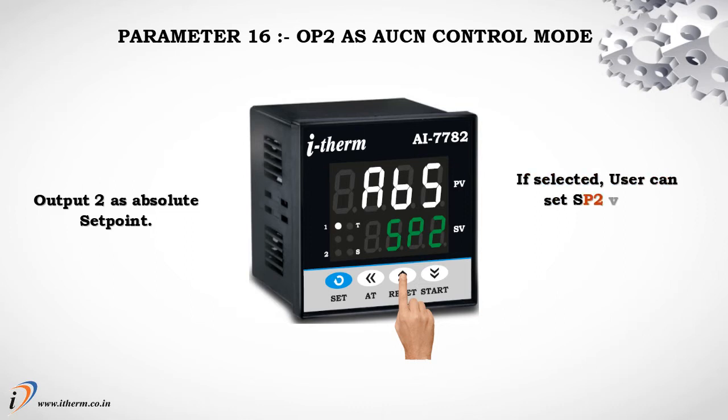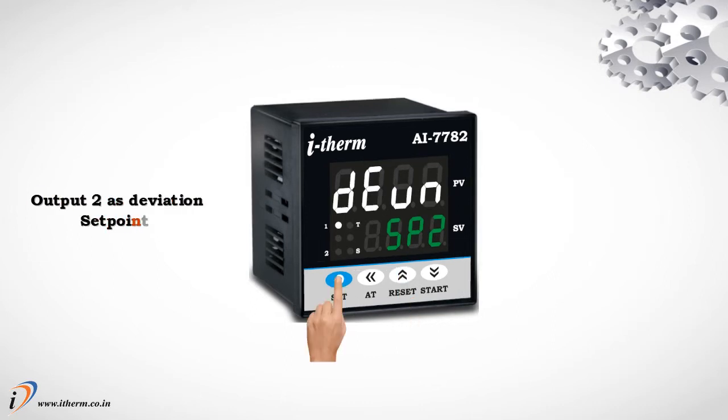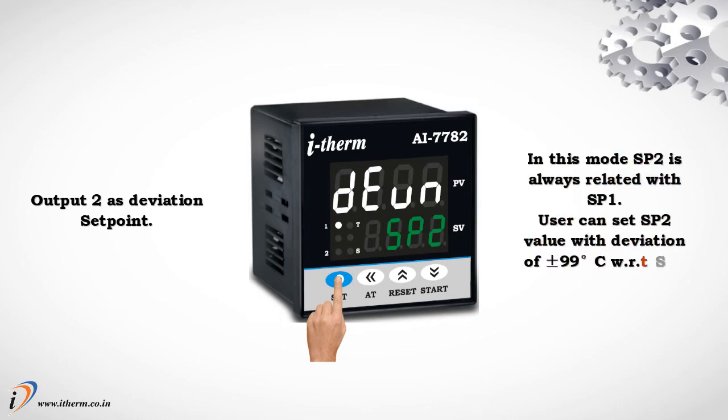If selected, the user can set setpoint 2 value independently, irrespective of setpoint 1. Output 2 as deviation setpoint. In this mode, setpoint 2 is always related to setpoint 1. The user can set setpoint 2 value with a deviation of plus minus 99 degrees Celsius with respect to setpoint 1.